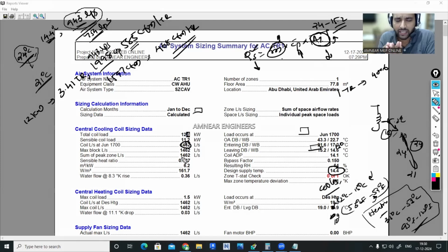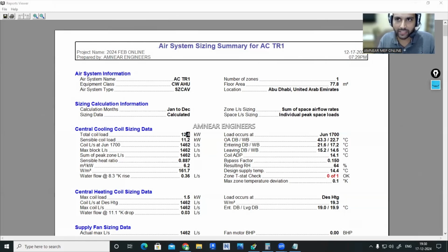So in most cases, the reason why the supply temperature is not matching the manufacturer-recommended 1 ton of refrigeration per 400 CFM is this. The supply temperature might be the reason in most cases. See, the sensible coil load is a constant factor only. We can't decrease it.